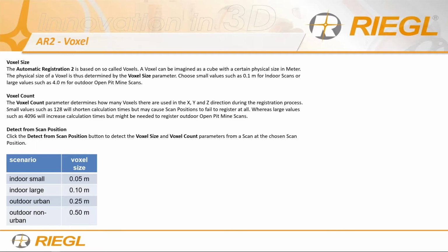I'm quite blown away how well this registration tool works. But as long as you follow all the recommendations that I had said at the beginning of my presentation, that you need to overlap, you need to move the scan quick, you need to move it short according to the object distance. And if you do all that right, if you select the right scenario, you're going to be very successful, and that's the message.